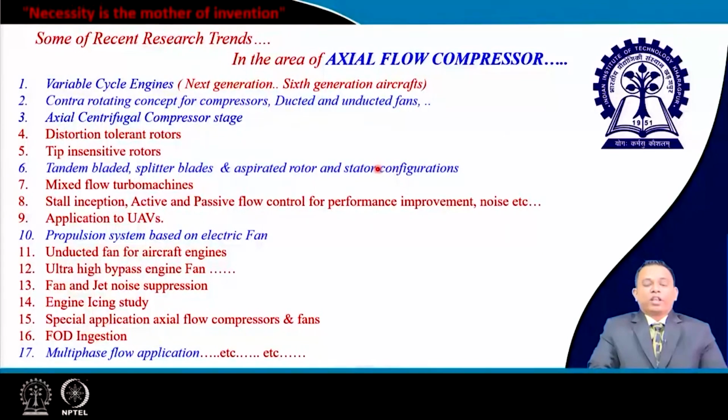Next is a counter-rotating concept for compressors, ducted and unducted fans. People are talking about axial centrifugal compressor stages, distortion tolerant rotors, tip insensitive rotors. Now this is of a different flavor. We know tip leakage flow is prone to happen because of the relative clearance between rotor and casing. Now the demand is for those kinds of fans or compressors which will not have any effect of tip clearance. So that demands a whole lot of understanding.